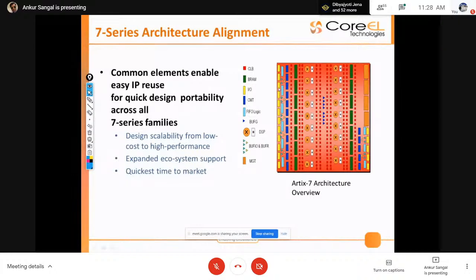Actually, Xilinx has given input output pins in 2 types. One is your high performance pins and another one is your high range pins. If we are talking about the high performance pins, we can call them MGT. MGT stands for multi-gigabit transceivers. This is available here, and this is your HR pins, the yellow one. Now, what is the difference between your HR and HP pins? If you want to work with more than 2 Gbps speed, you need to use your MGT pins, multi-gigabit transceiver pins, or otherwise you need to use the yellow part, HR pins.